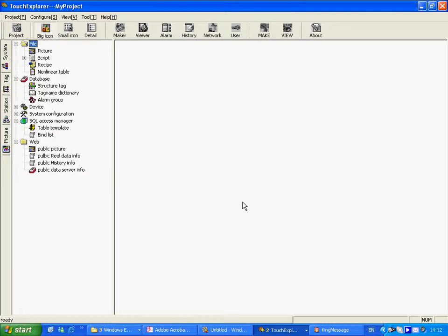The hardware, device or software program with which KingView exchanges data is defined as the external device, or I/O devices. For real-time data communication between KingView and hardware, we must define an external device and a corresponding tag in the developing environment. After the connection between the computer and external device has already been set up, the device configuration wizard will guide you step by step through the connection process. For example, how to set up communication between KingView and the simulated PLC.